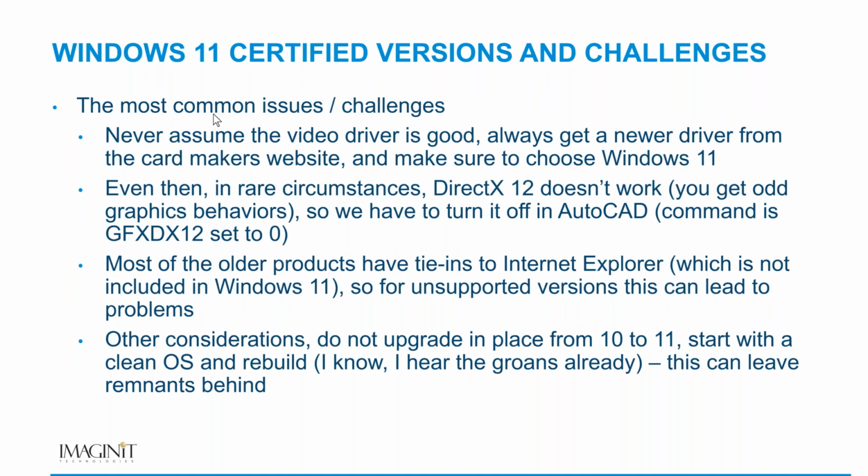Now, let's talk about some of the most common issues and challenges. The first thing I'm going to talk about is never assume the video driver is good. Even on a brand new machine, never assume that. Always get the newer driver from the card maker's website and make sure to choose Windows 11 driver. What I find is a lot of people have Windows 10 drivers and not Windows 11, and that does cause some issues. And even then, in some circumstances, DirectX 12 does not work.